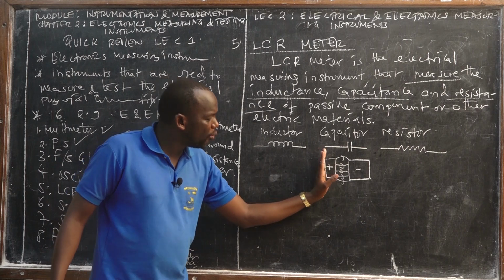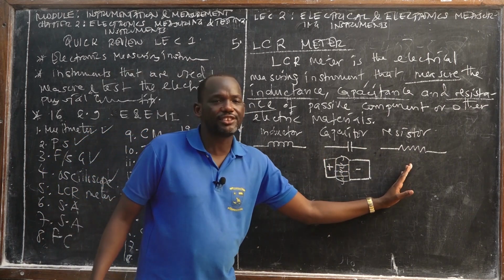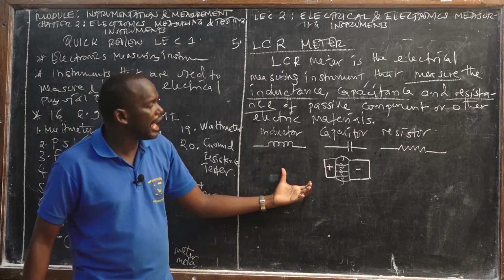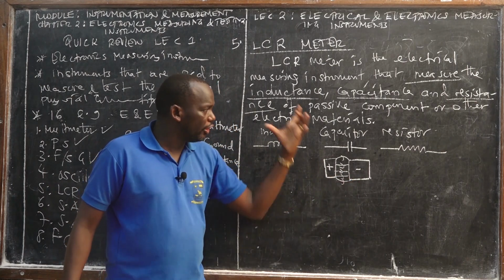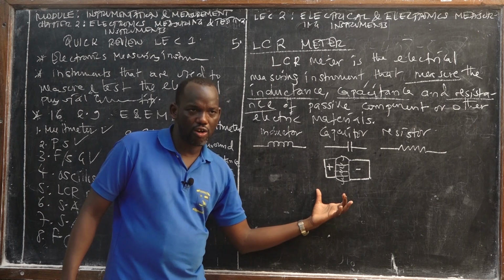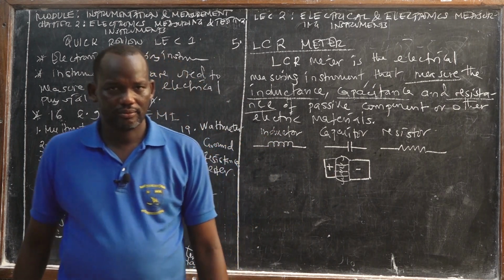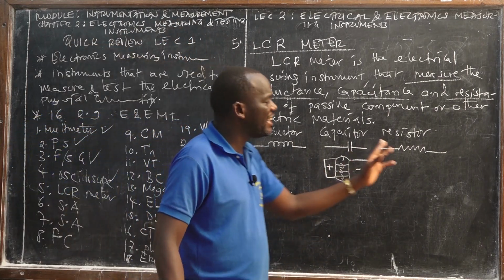This might be one side of the sensor that interfaces with the real world, and this is another side of the sensor that gives the electric signal. So you may use an LCR meter to measure the capacitance of these two materials, not of the capacitor, no, but of the material that behaves as a capacitor. Are we together?